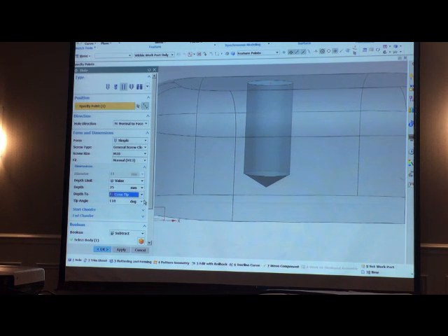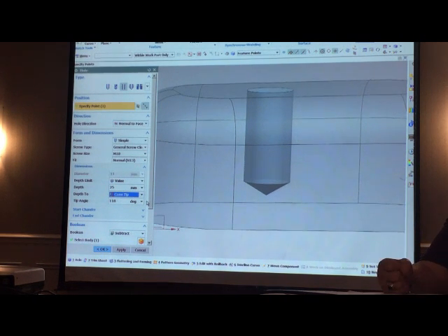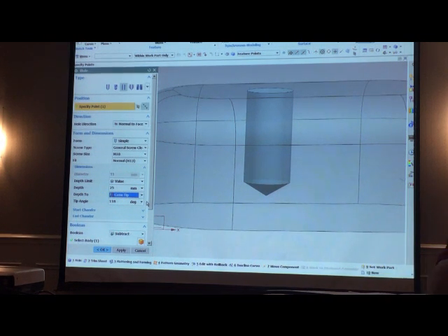This is one of those cases where the design intent doesn't match what you give manufacturing, because manufacturing has to be able to measure its results. They cannot measure accurately to the bottom of that tip. I can design to it, but they can't measure to it. But now at least I can do it without having to trig it out myself. Let the software do the trigging. It's, after all, a computer.